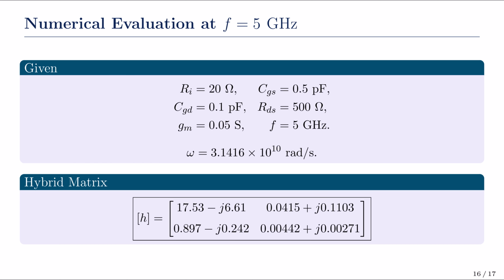We have therefore completed the three examples of the hybrid parameter extraction. In each case, the same general procedure was followed. Write the port equations, apply the appropriate defining conditions, and identify the h parameters. This concludes our study on hybrid parameters.